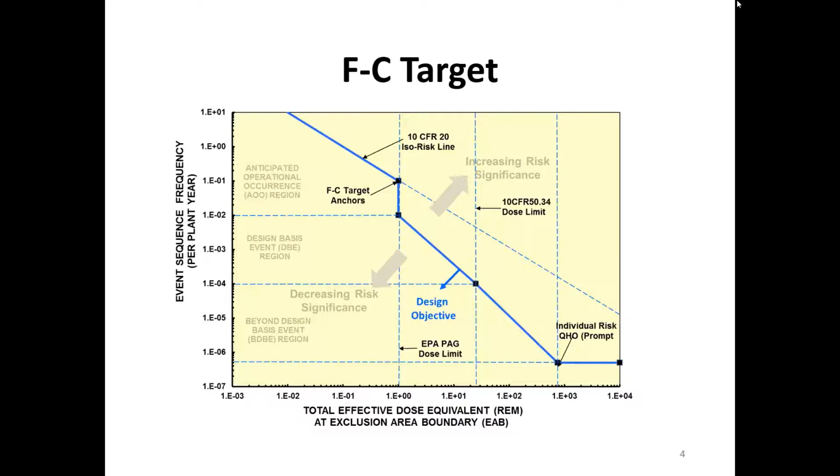So I think there are two. In the design, you design to a big event like one in 10,000 or something. But when you do a risk assessment, you look at events of all sizes. You look at the full range, from a low level of seismic, say earthquake acceleration, up to the high levels up to 2g or something. So you look at the full spectrum of hazard when you compute the risk. You look at the plant impact of all different motions. And generally, the low earthquakes don't cause that much damage because these plants are designed for very light earthquakes. But you do look at that.